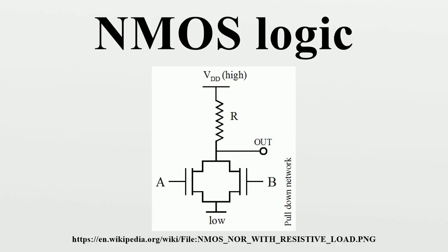The major drawback with nMOS is that a DC current must flow through a logic gate even when the output is in a steady state. This means static power dissipation, i.e., power drain even when the circuit is not switching. A similar situation arises in modern high-speed, high-density CMOS circuits, which also have significant static current draw, although this is due to leakage, not bias.